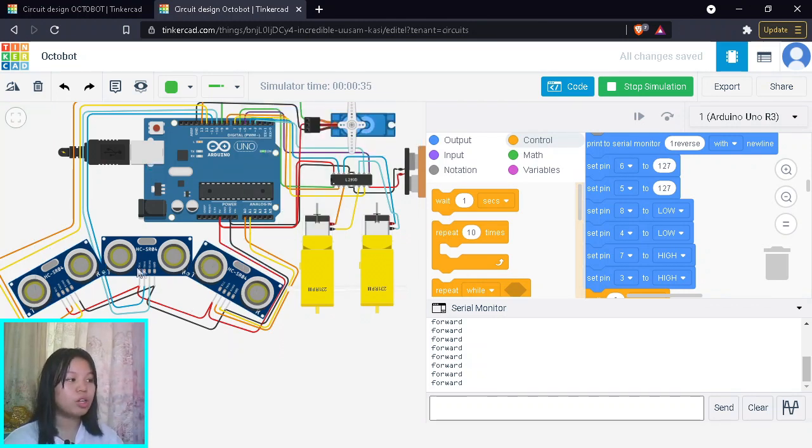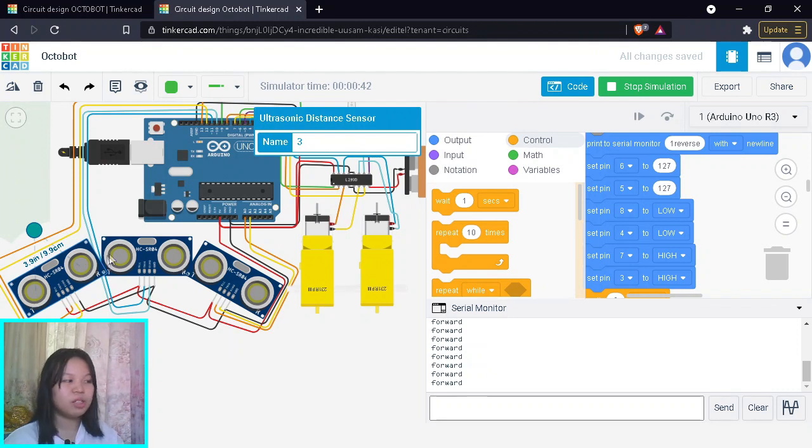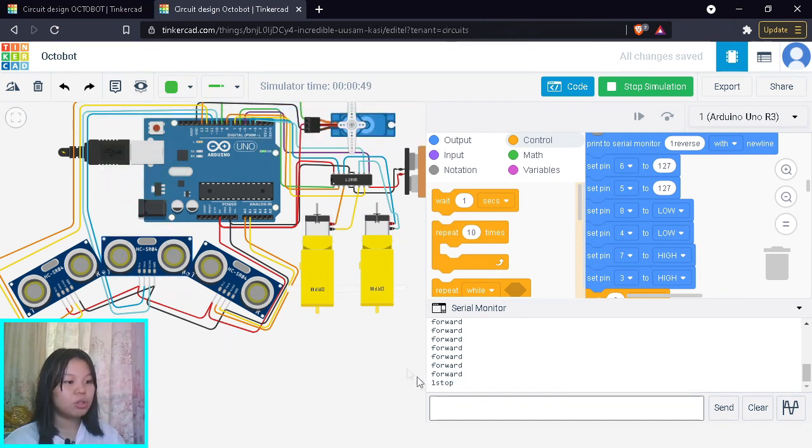From the program we know that it first checks the front detector, and only after that checks the left and right detectors. My hands wouldn't be fast enough, so we're going to set up scenario 3 first. Looking at the second scenario, less than 20, it makes the first stop at 0 RPM. It reverses at half the speed, so negative RPM at about 117 RPM now. After checking, it goes to the third scenario. It steers towards the right, and you see both are moving positive RPM at half the speed, so 117 now. That is scenario 2 with scenario 3 combined.